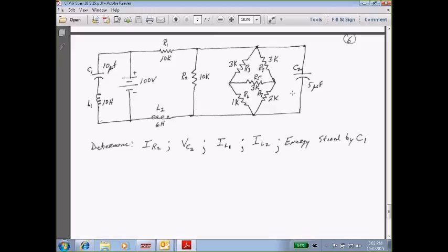Okay, now let's find our total resistance. Right here, you've got 1K. You've got 1K here. Then you're going to come down with 1K and then 2K. Well, let's look, the top 1K is in series with the rest of those. So you've got 1K in series with 2K, that group in parallel with 1K in series with 1K.